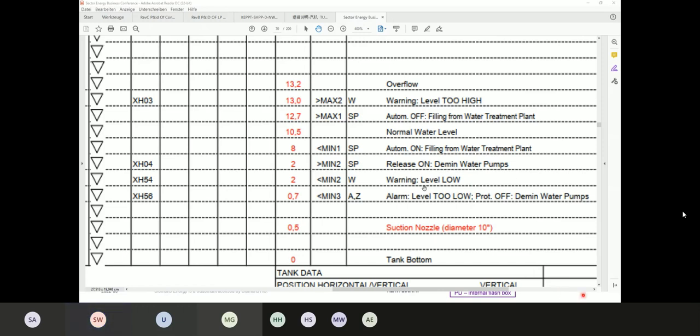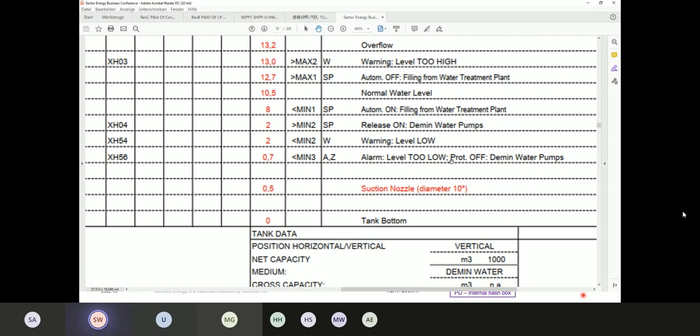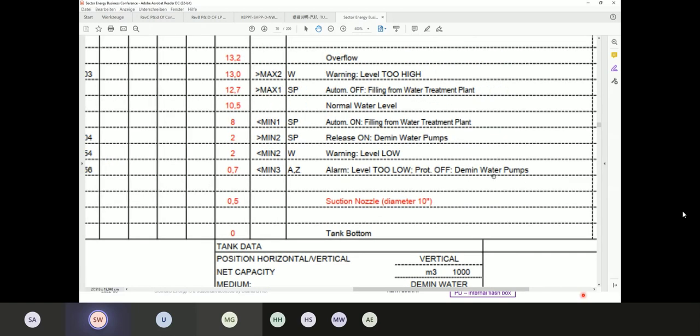And then it should be working like this. So somewhere there should be a protection in. And this is just for the suction side pressure. When there's less than 0.7, then we're getting the critical parts. There could be then cavitation coming, and this we want to avoid.